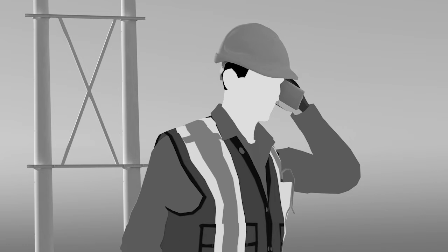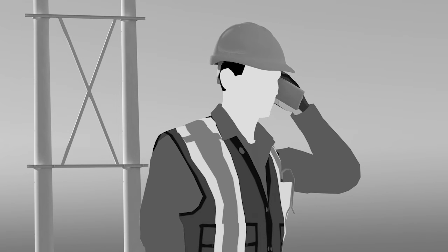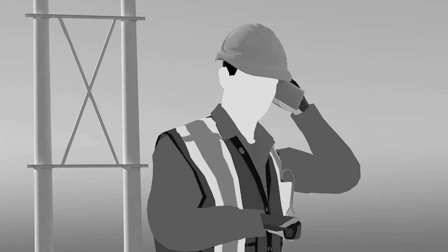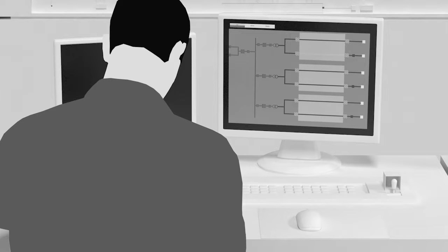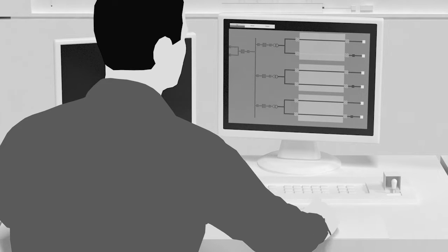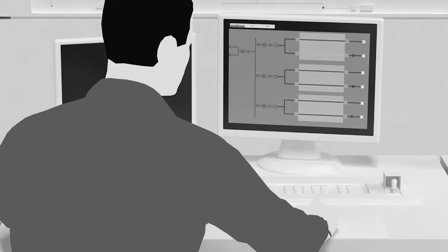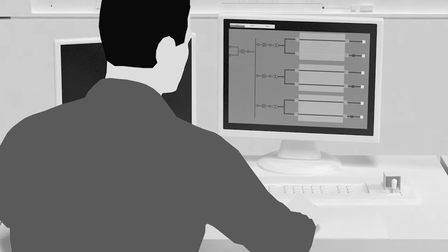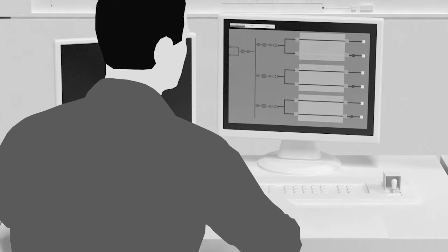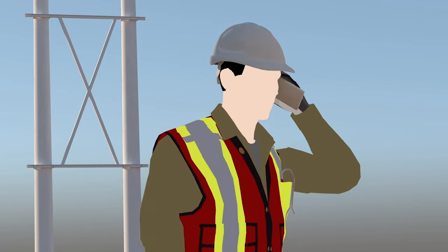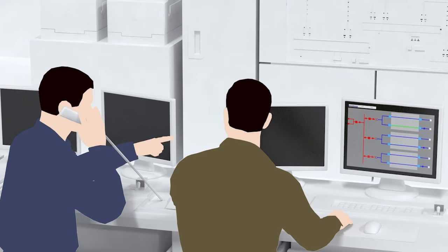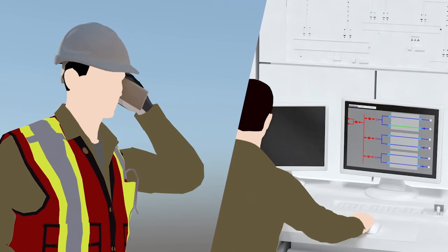In this case, the worker was supposed to finish their work and return to the ground, where they would contact the coordinator by mobile phone, who would then relay to the substation that the work was completed and it was safe to turn on the power. However, there was no notice even when the work was scheduled to end, and since the coordinator had been away from their desk, the substation worker decided on their own to turn on the power, causing the accident. Wearing a safety belt and maintaining good communication between the site and the HSO will help prevent work accidents.